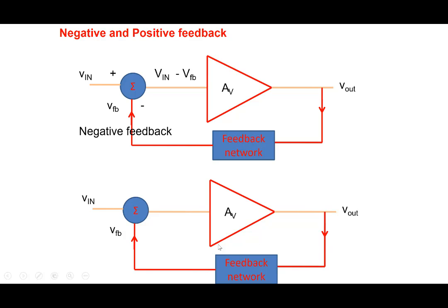On the other hand, we could also take it here such that we can add them up. So the voltage which is fed back is in sync with, or in phase with, V in, and so it adds to it, and we call it positive feedback.